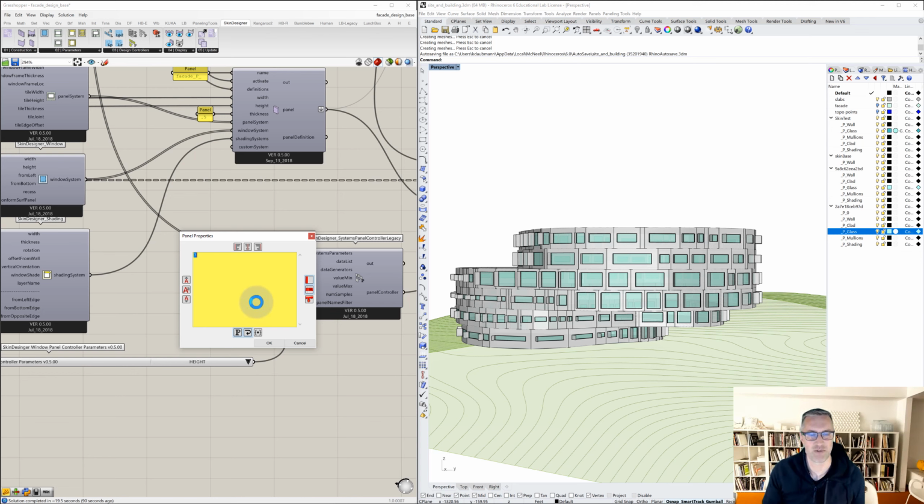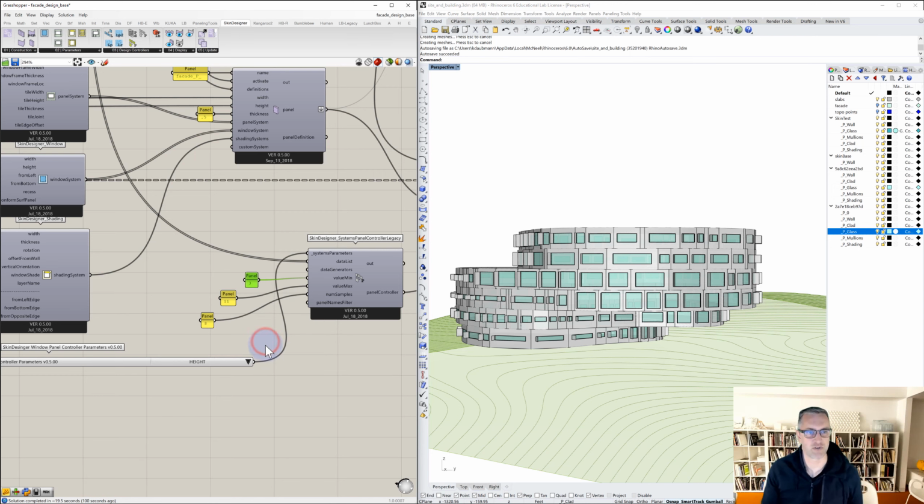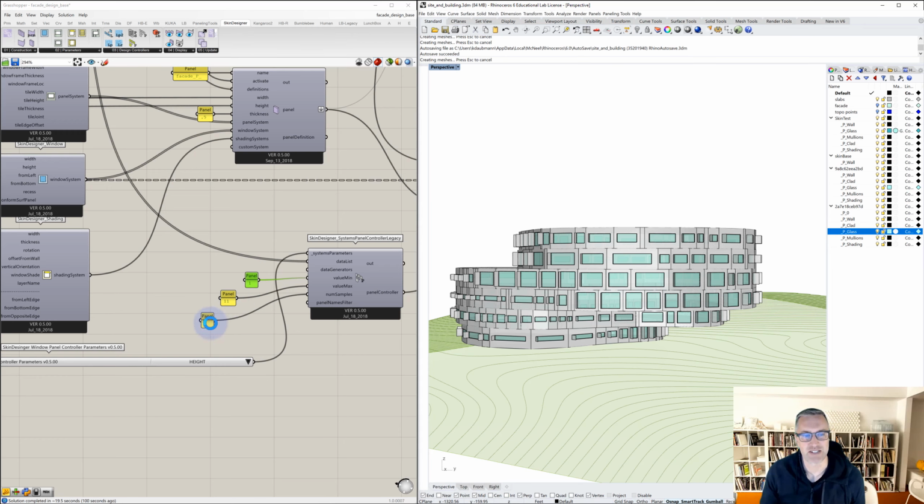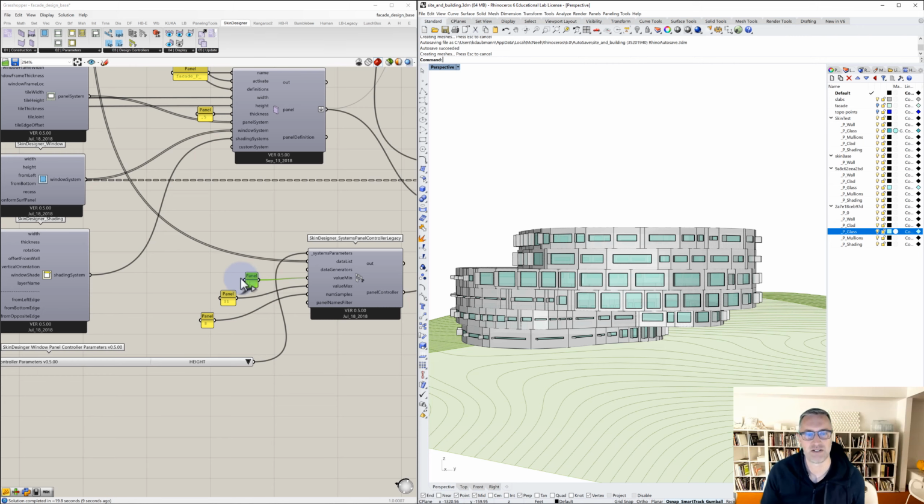And this would have been a moment where we should deactivate, because now every time we make a change, we have to wait for all of the panels to be updated. But we could be a little more extreme. And I will deactivate. What I'm going to do is change, we just changed 3 to 1. I'm going to change 11 to 12. And then I'm going to make the sampling just 2 versions. And what that should do is give us either a 12-foot piece of glass or a 1-foot piece of glass. Now we can see 1-foot pieces of glass through here.